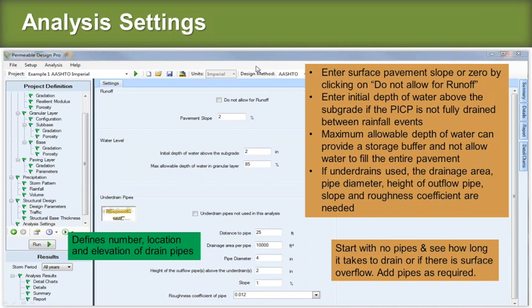The municipality may say you have to do pre-development, or you may have to just capture an inch plus the volume from a 2-year or 5-year storm, with the first inch for pollution, and then beyond that for a 5 or 10 year, whatever your storm. That's obviously a specific depth, so that's input early on in the program.